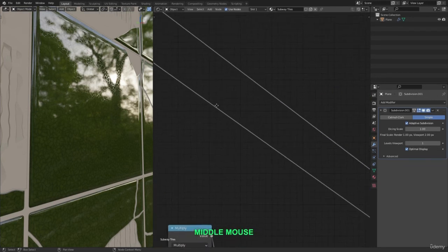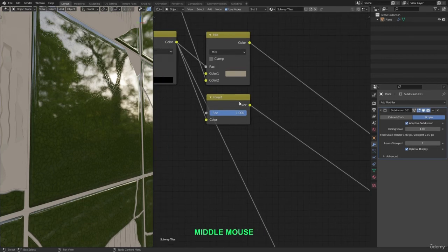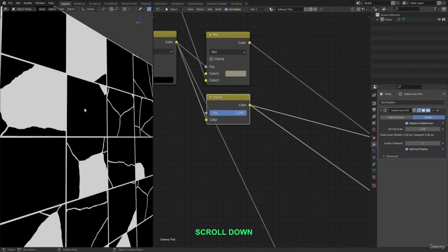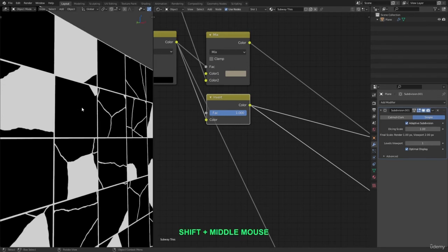And that roughness map, if we follow this up, is coming from this invert node right here. Now, the black values on this map give us 0 roughness, so the tiles have perfect reflections. I want the option to have more blurry reflections, so we basically just need to brighten up the black values to do that. And for that, we'll use a math node.